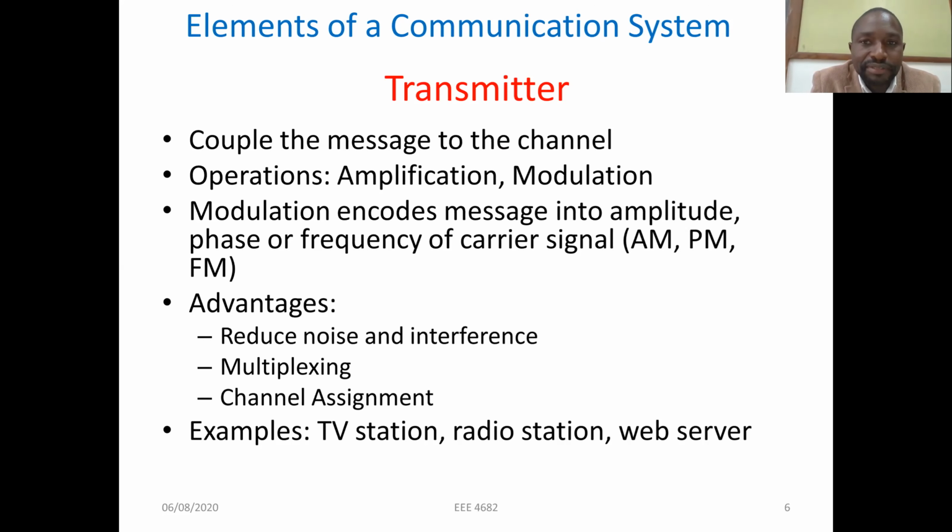Modulation also encodes messages into amplitude, phase, or frequency of the carrier signal. And so we may talk of amplitude modulation, phase modulation, frequency modulation when we refer to analog modulation schemes, or we may be talking about other digital modulation schemes such as QAM and the like.